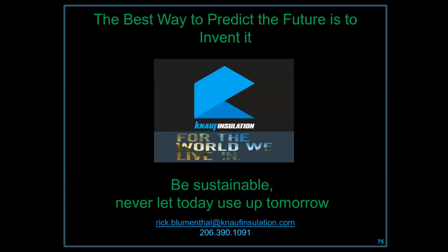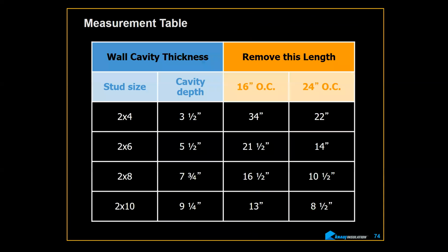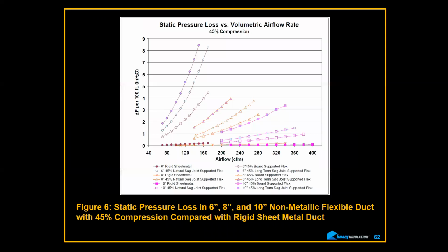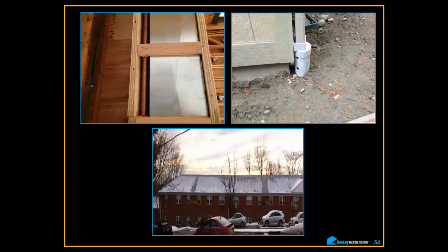Again, fine in the hot, humid climates, no problem with it. Condensation control up top, fill the cavity with your favorite fibrous material that you like, and put your air barrier in there, remembering that that assembly, let's see if I can find that real quick. Looking for that roof assembly.